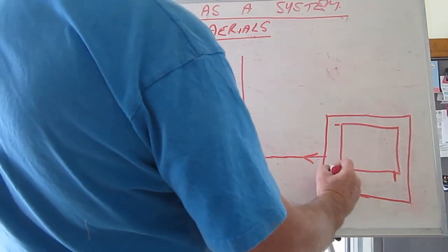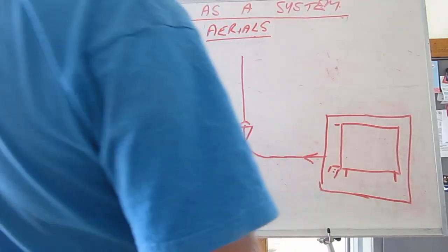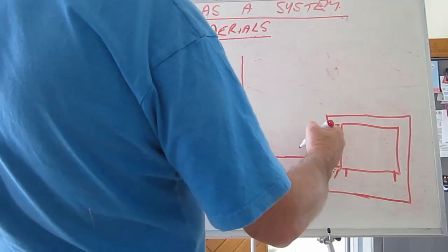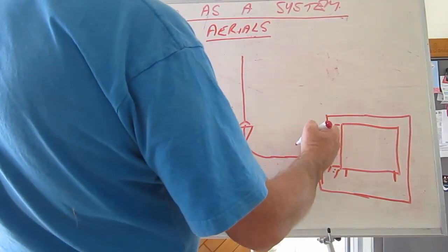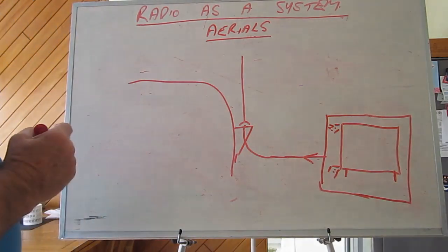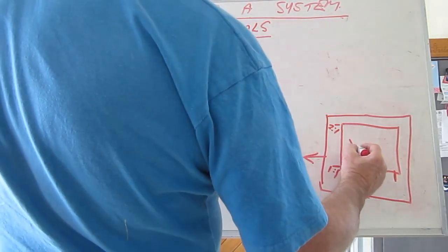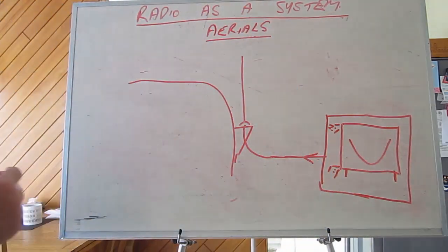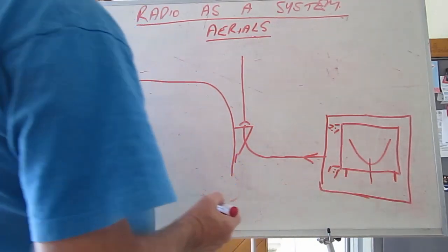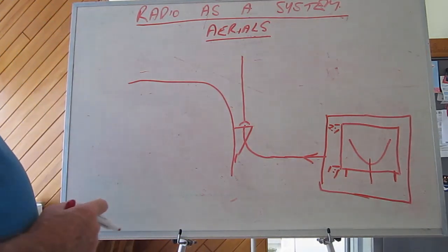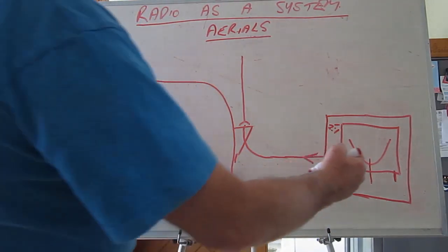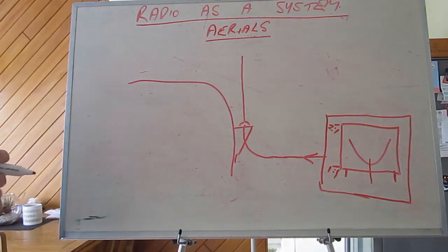Now obviously down at the bottom, a ratio of 1:1 is a perfect antenna. You might have this as bad as 2:1 or 3:1 up the side here. Let's go 2:1. And a typical plot will look like this. At the center frequency here, you will have a relatively ideal VSWR. It will not be 1:1, but it will be quite close to 1:1. And then either side of this, you will have a rising VSWR.